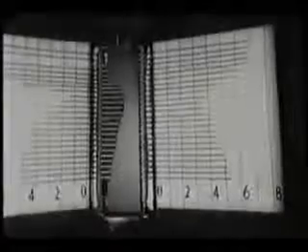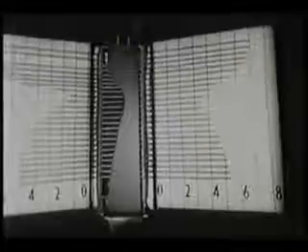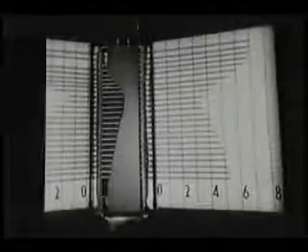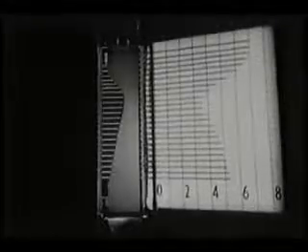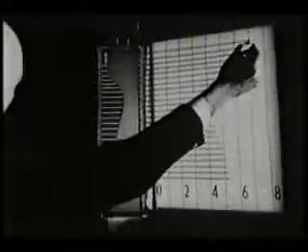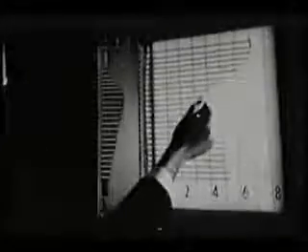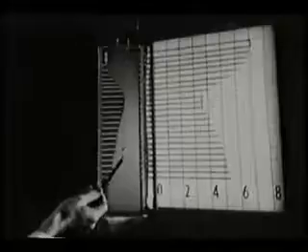Now the flow is steady. We will look first at the pressure distribution on the straight wall. Continuity tells us that because of the area contraction, the velocity increases to the throat, and this causes a pressure drop. Downstream of the throat, the area increase produces a velocity decrease, and this causes the pressure to rise.